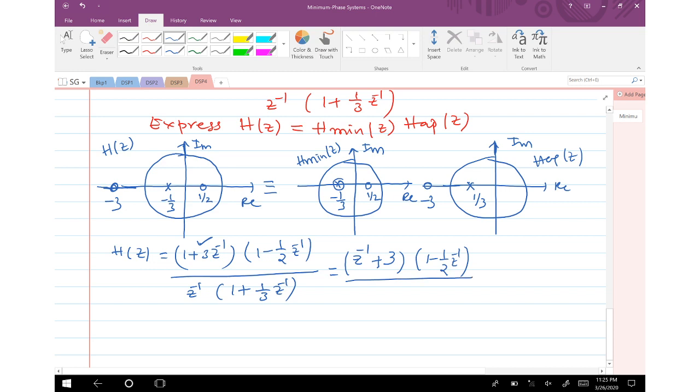Okay, and I'll talk about z inverse, we will come back to it a little later, but let me for the time being put it in the all pass filter. Okay, so here z inverse plus 3 I had kept there, so in order to cancel that I should have z inverse plus 3. I haven't included z inverse in the minimum phase, so let me keep it here in the all pass. Okay, and what else is remaining here? Anyway, 1 plus 3 z inverse is there, right?